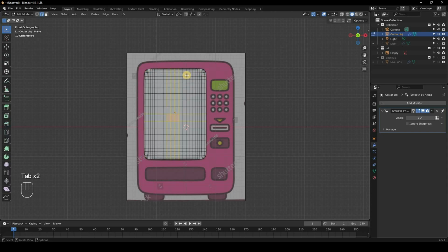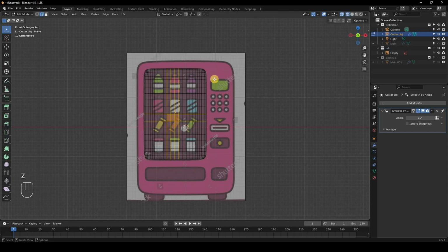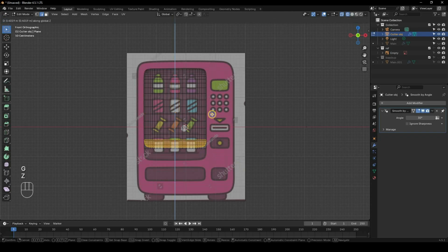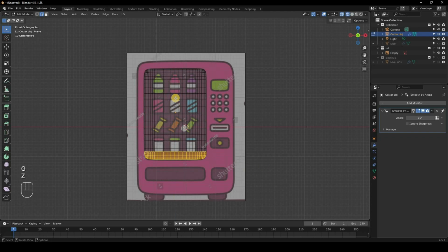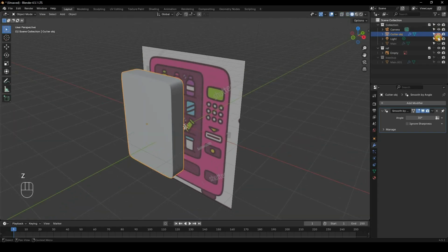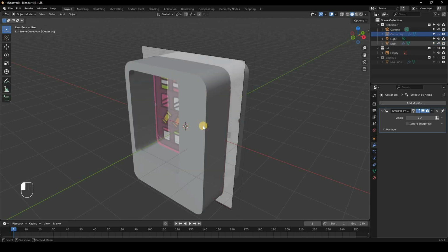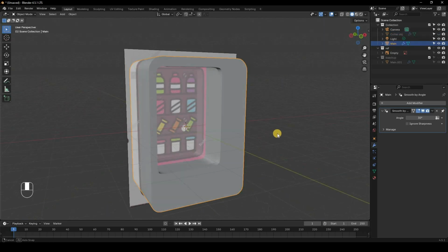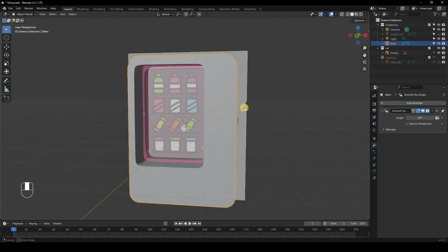After dissolving them, you can move these to the bottom part and scale the shape. But first you need to dissolve all these extra vertices, or you can just create a new cutter object. The shape will be similar in terms of depth, and you can use the boolean modifier again to cut in an object like this.